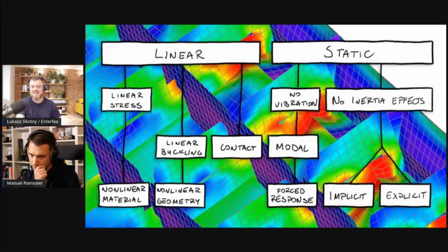So you can easily calculate a structure that already died and be blissfully unaware of it. So that's also a drawback, but to me it's the bigger one, because I would rather have problems that I know that I have. So if I get stresses higher than yield, at least I know that there is a problem I have to fix. But if we would make a popularity contest of what is the biggest problem in FEA, I'm absolutely certain that stress higher than yield would win over stability issues by a landslide. Yeah, it's the first thing you see.